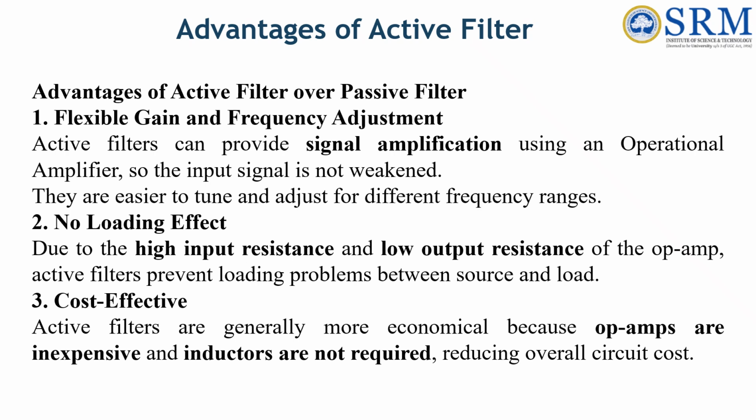No loading problem. Loading occurs when one circuit stage affects another. Since active filters use op-amps with high input impedance and low output impedance, signal transfer becomes efficient without affecting connected devices. Cost effective. Passive filters often need inductors, which are bulky and expensive. Active filters avoid inductors and use low-cost op-amps, making them smaller and cheaper.